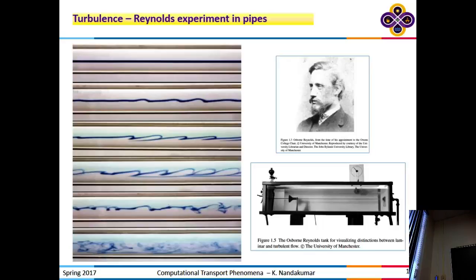And this is the point I think you raised once, right? In turbulent flow, all the velocity components are non-zero. We cannot make an assumption about saying Vz is a function only of r. All components are spontaneously developing through transfer of energy from one momentum direction to the other momentum direction. So you have the so-called fluctuating velocities.